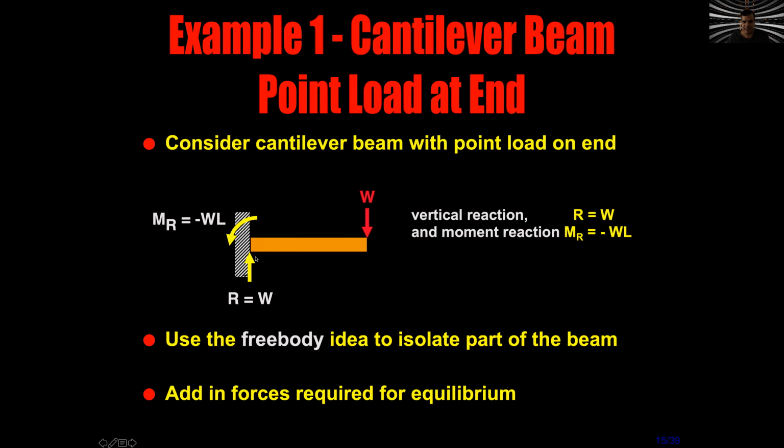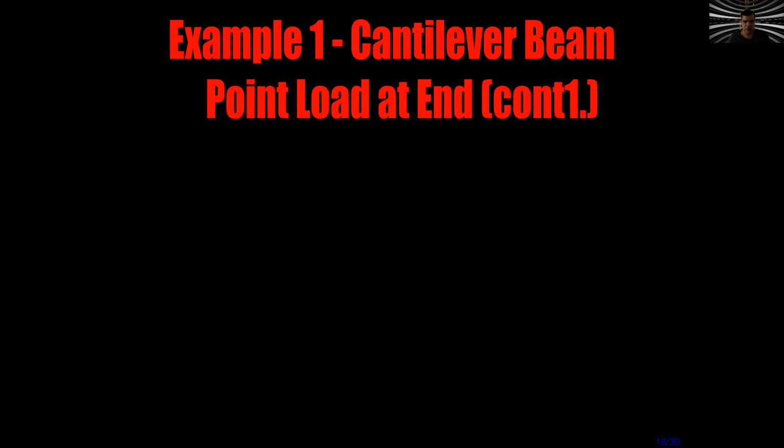Well, in the extreme of this beam, we have two forces in order to get equilibrium. W multiplied by L, that is force multiplied by the distance, that is the moment there, and also a force W that needs to push up. If not, that beam will fall down. Well, we need all those forces to have some kind of equilibrium.